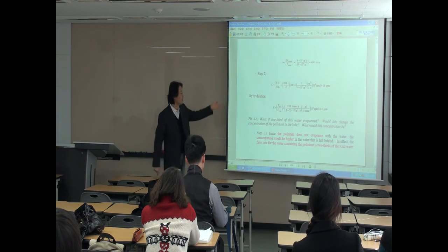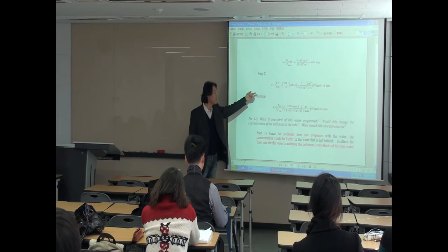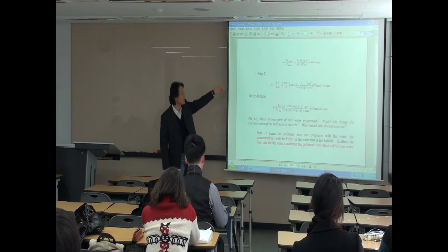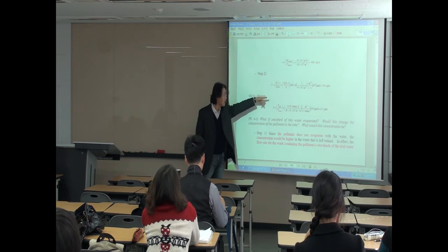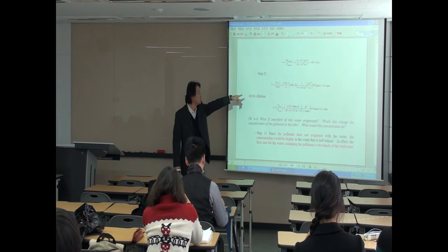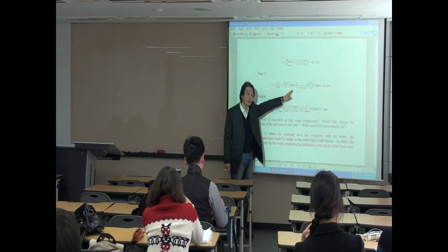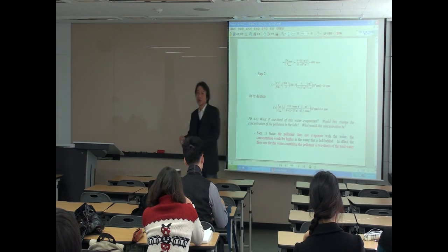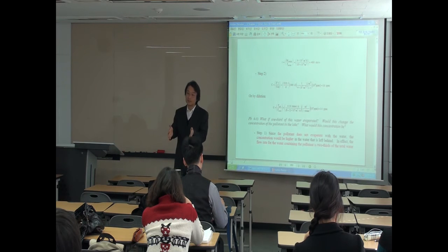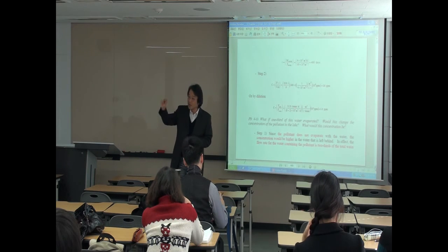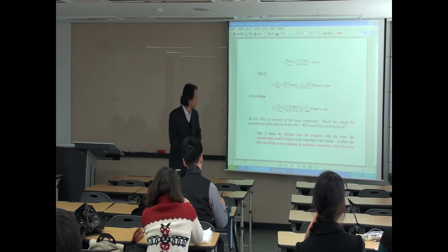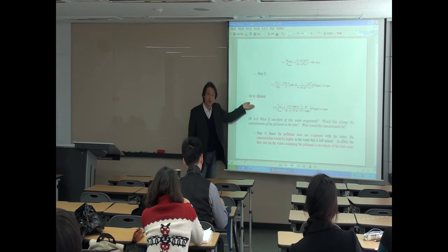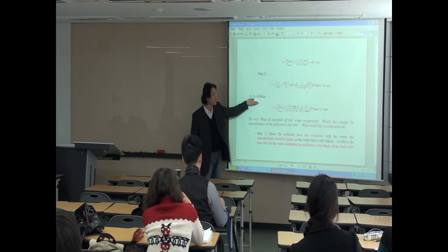Then you do the same calculation for obtaining concentration. So just using the new residence time, 400 days, you can have 1.6 ppm. Because if you provide more water into the lake, the concentration of the salt can be decreased. Right? All right, and then you simply calculate and estimate the concentration by dilution.